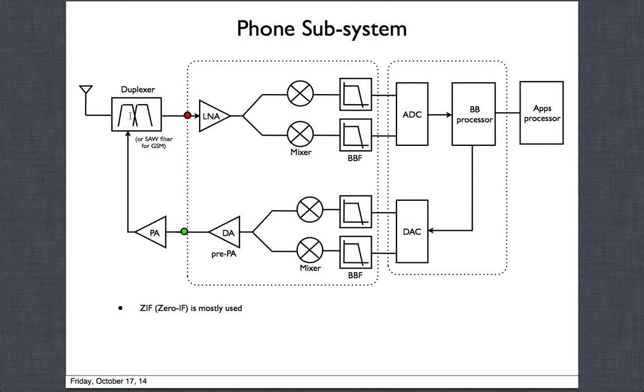So what is the difference between the two? Strong to weak signal: 110 plus 26, which is 136 dB, or let's say 140 dB as an example. 140 dB is 10 million times. So the receive signal is roughly 10 million times smaller than the transmit signal. If you have a strong transmit signal and the receive is close to it, it will wash it out. This hardware will probably not be able to distinguish between a signal which is 10 million times stronger and this little, teeny tiny weak received signal. That is the reason why we need these filters.